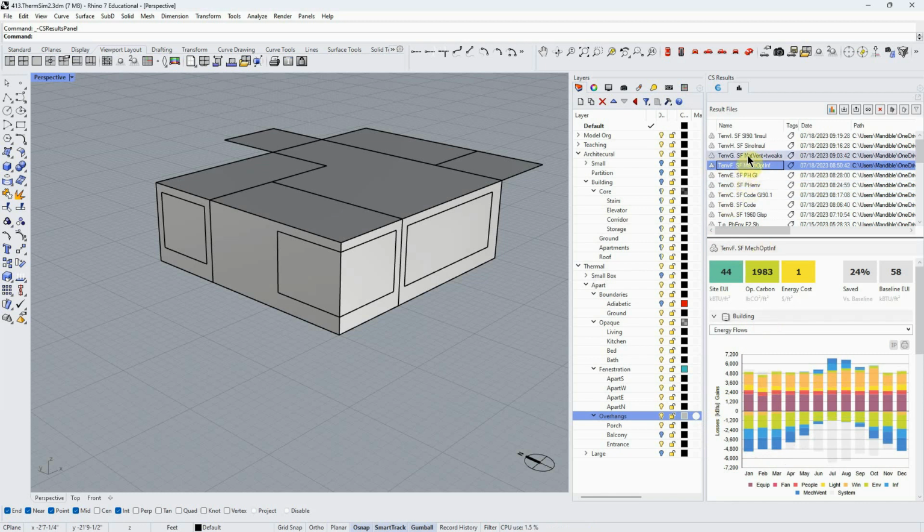Then the next thing I did was I added natural ventilation. I'll do a whole video on that. That knocked us down quite a bit too. And I also just tweaked some things using my own knowledge. I think this is when I put in a photovoltaic control of the lighting, so that we have lights turning off when there's enough daylight. I tweaked the insulation slightly, etc. And we were able to get quite a bit more improvement out of it.